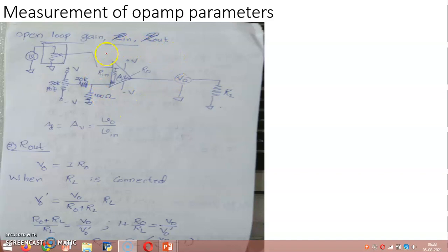That open loop configuration is shown here, and in any circuit that you draw using or involving operational amplifier, you will have to show this plus VCC and minus VEE power supply terminals, though it's not shown in your textbook. Now we will have to supply this amplifier an extremely small signal having a signal strength of the order of preferably say microvolt or a few millivolts.